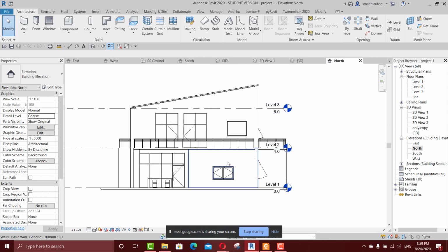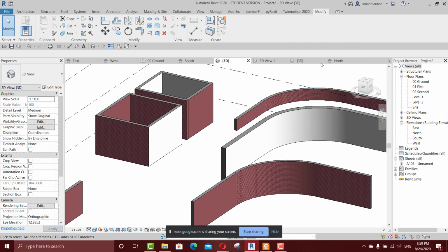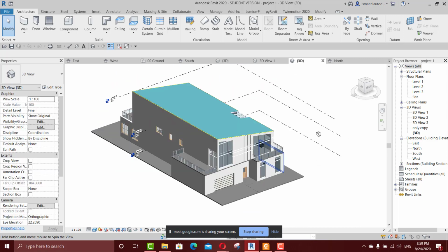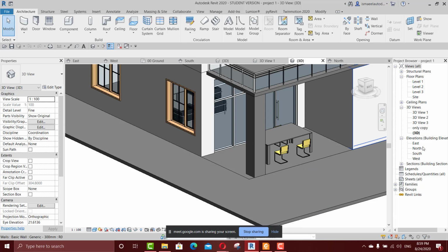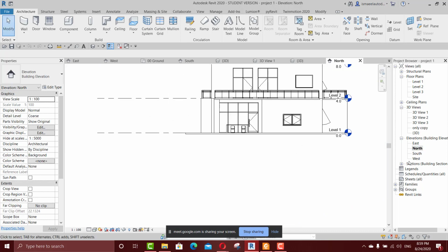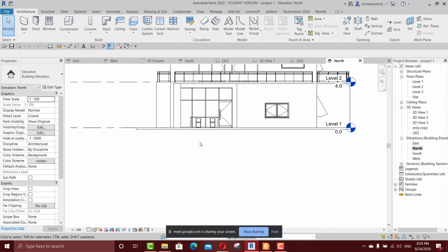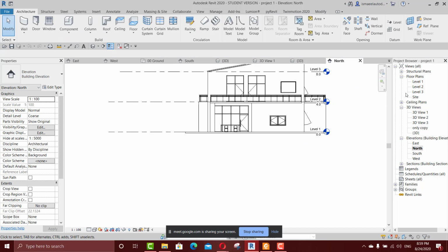If I do have stairs, for example, outside, I have to put another level. I wanted from a level to another level or a wall. I have to create a level for it to be able to draw it. Okay, so this is the point of creating the walls.